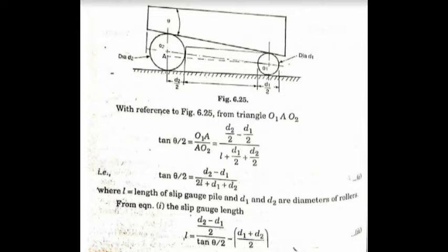So, the use of precision balls and rollers for determining both linear and angular dimensions. Suppose you want to find out the angle of a tapered piece. By using rollers of different sizes or slip gauges and a dial indicator, we can measure the angle. Here the two rollers whose diameters are known and slip gauges are placed on the surface plate as shown in this figure. The rollers may be clamped in position against an angle plate by using C clamps. The work is then placed on top of the rollers and clamped against the angle plate.